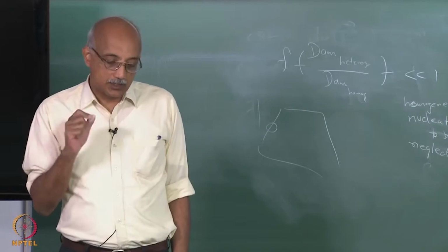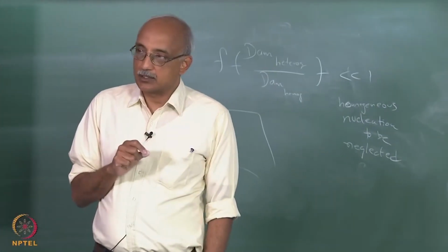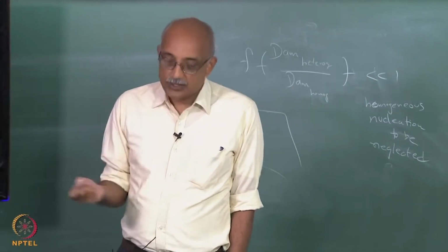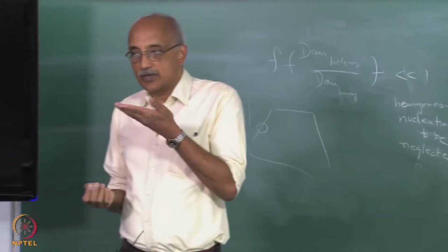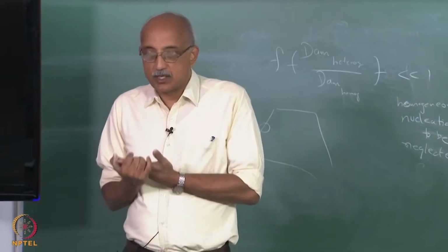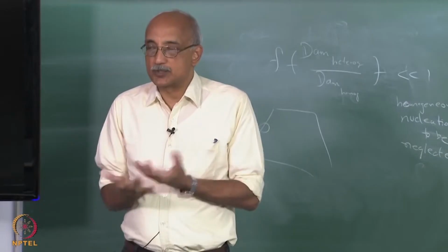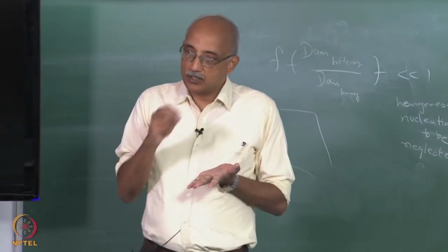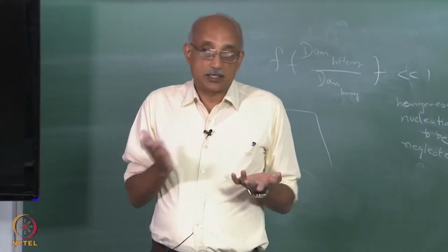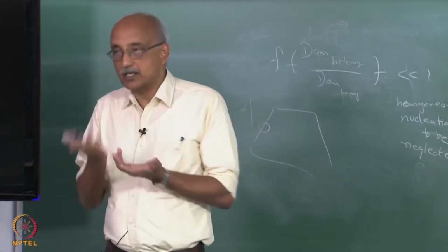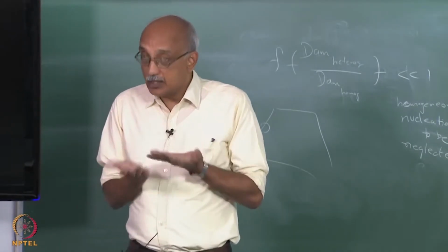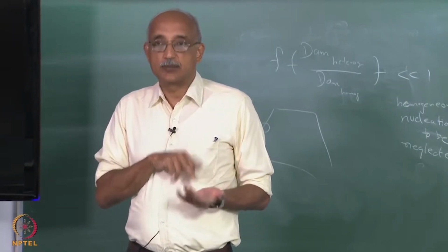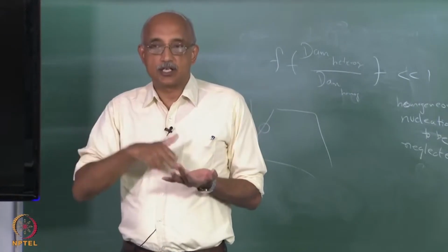Here again the considerations are very different for an aerosol CVD reactor compared to a vapor CVD reactor. In a conventional CVD reactor, you can assume that when a vapor molecule strikes the surface, as long as there is a site available for adsorption, the vapor molecule will get adsorbed, right. But in the case of small aerosols striking the surface, that is not necessarily true. Even if there is a vacant site and even if there is a chemical affinity between the particle and the substrate, depending on the angle of incidence and the velocity of incidence, the aerosol can actually rebound.